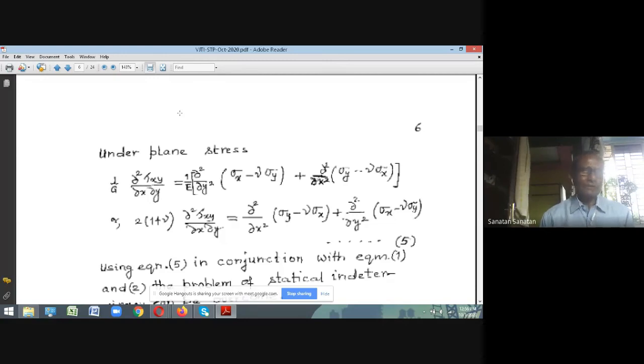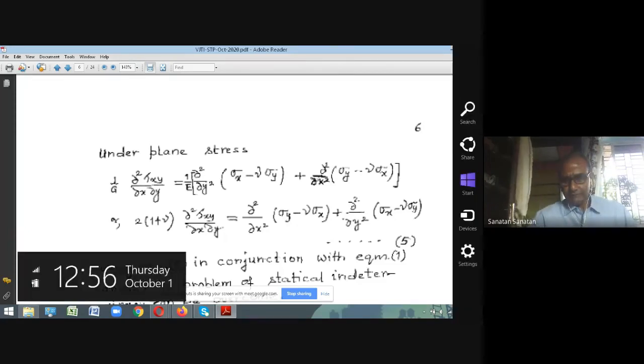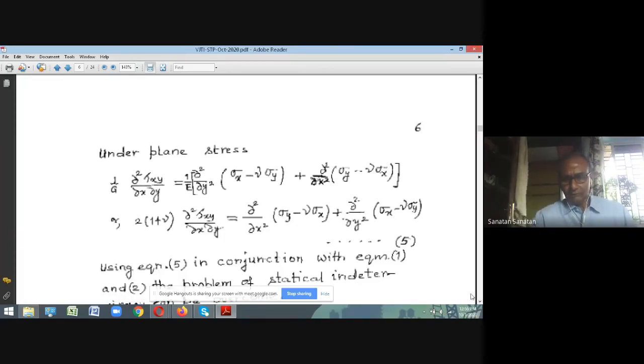So therefore, you see that exactly in the case of strength of materials problems, we had two unknowns, one equilibrium equation, one compatibility condition. In the case of two-dimensional stress analysis, we have three stresses as unknowns. We have two equilibrium equations plus one constraint condition or compatibility condition, which is also involving the three unknown stresses. So therefore, our problem is solved. So we have three stress functions which are related by compatibility conditions, and therefore you see the problem of indeterminacy is gone.